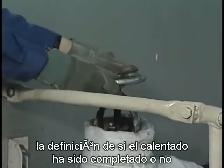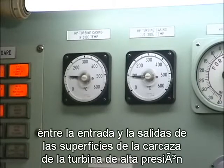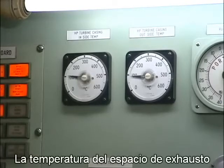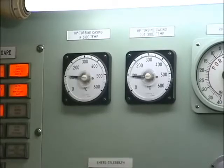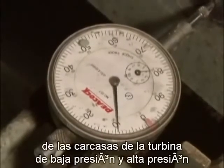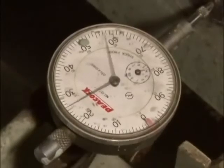Judgment of whether warming up has been completed or not is made by the difference in temperatures between inner and outer surfaces of the high-pressure turbine casing, the temperature of the exhaust space of the low-pressure turbine, and by determining the expansion of the low-pressure and high-pressure turbine casings by means of respective dial gauges.